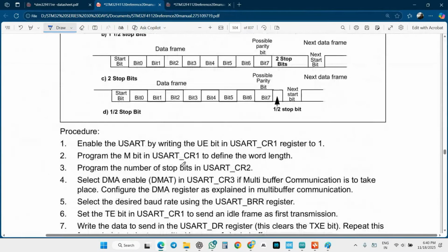In this transmitter procedure, first of all, they say enable the UART by writing the UE bit of the CR1 register. And again, I am telling you, they won't give the structure of the programming skill. We have to read it again and again and enhance the skill. Whatever is set one time, you write outside the loop, in the configuration side.